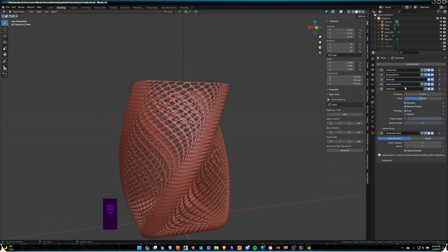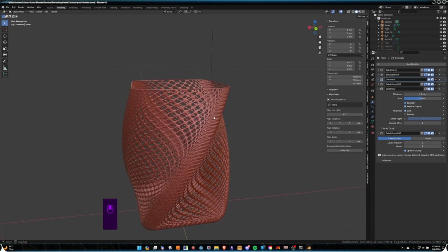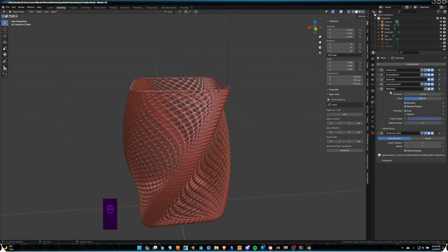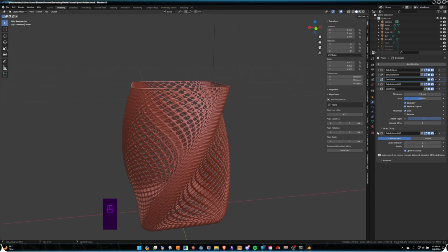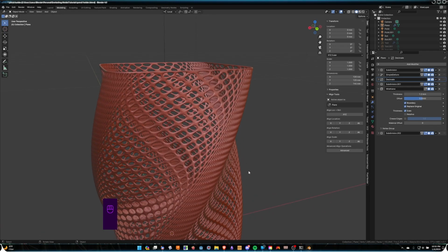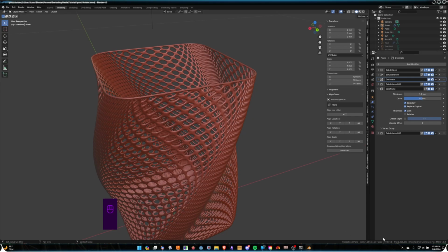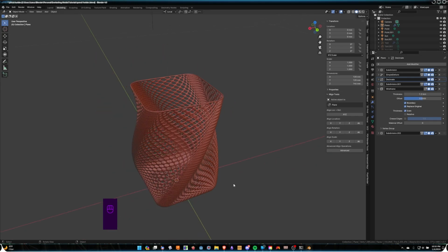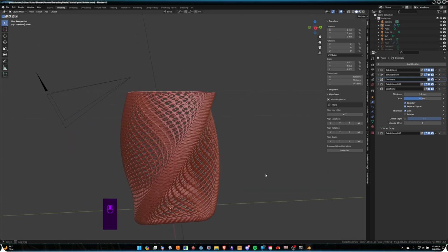You might want to work on your cooling. This is actually kind of a prototype Benchy in a way because it has so many overhangs and so many corners, lots of little gaps to fill. But you might notice that, and I'll show you in the slicer in a moment, you might notice that some of these overhangs are hard to deal with without using supports. This is a print that I probably would recommend using a soluble support with.